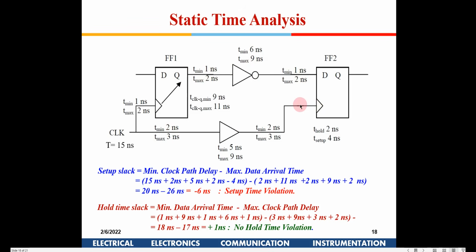Okay, the clock is coming early in the best case, and in the worst case the data. So that will give me the total worst case scenario. I am repeating it to find out the worst case setup scenario. I am going to take the fastest clock path and the worst data path. Okay, so the fastest clock path is 50 nanosecond, which is the time period, right?